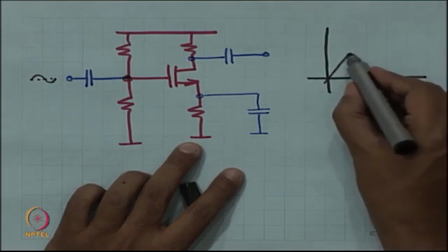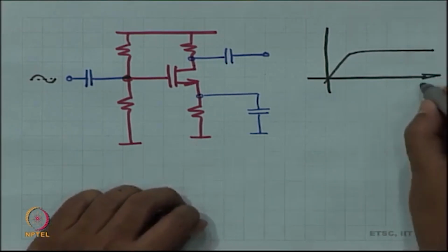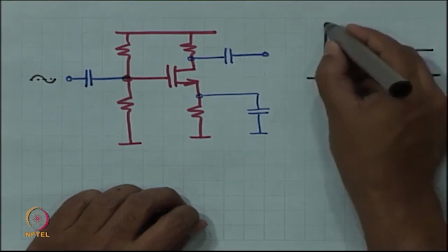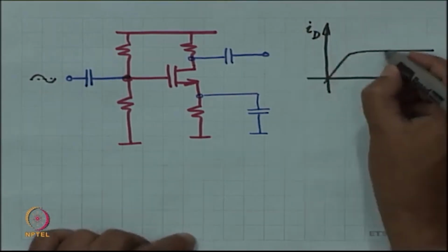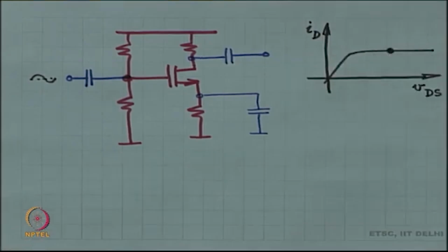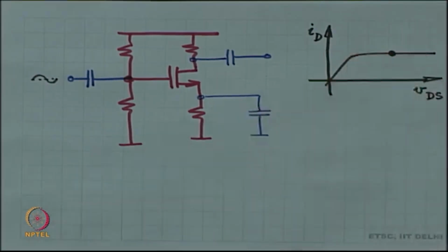So, remember you had set the MOSFET at an operating point, right, but you need to remain in the flat region of operation, otherwise the slope of this line is going to become low and therefore, the gain is not going to be enough and so on and so forth.